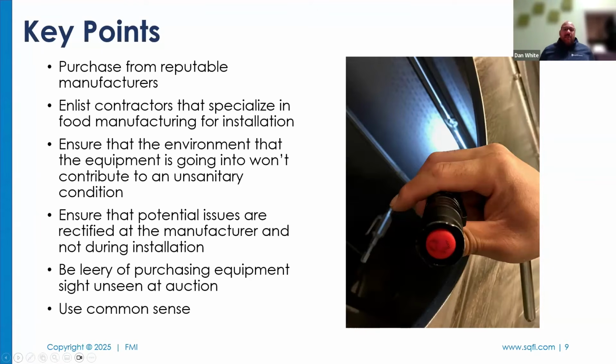So I purchased this piece of equipment, and the exterior of it looked phenomenal. I mean, polished, great, everything like that. But once I tore into it, that's a bad weld right there. They'd overheated it, and instead of replacing that piece of piping, which is part of a spray bar, they just figured, hey, it's inside of it, we're just gonna let it fly. We caught it, and we had to cut it out. It took a little bit of time, but we got it cleaned up.